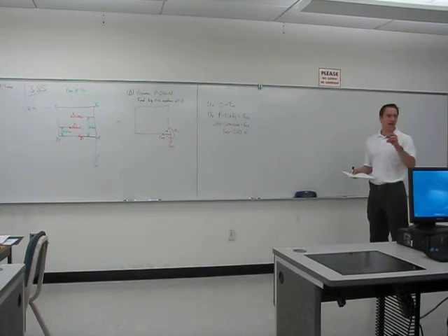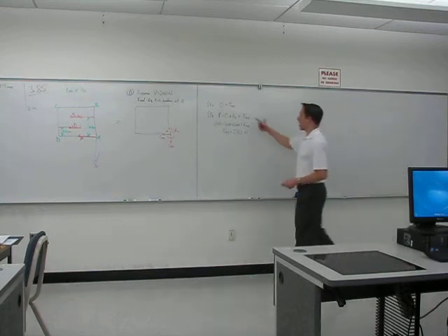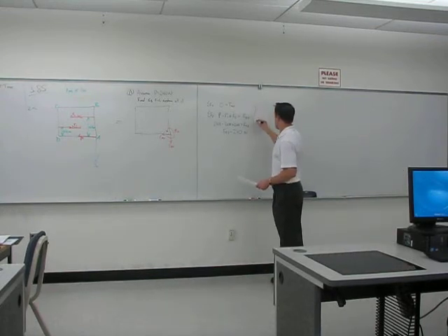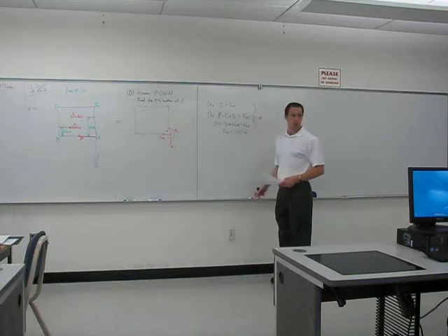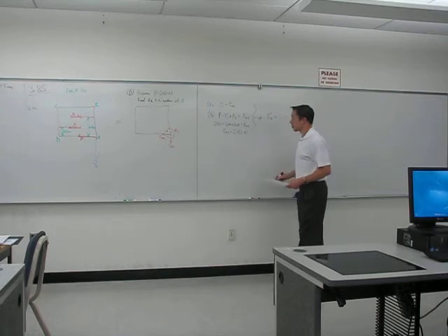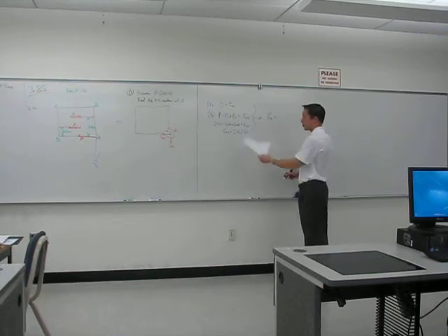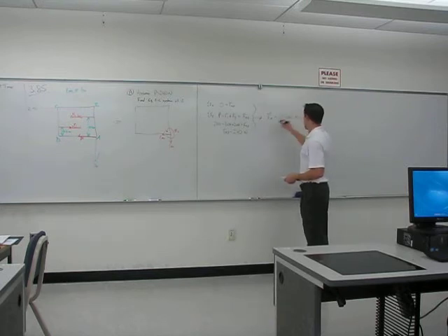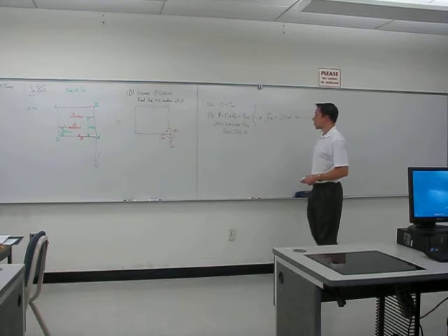So right now, I know what the force is that needs to act at the point A. If I just combine the two results that we found here, what this tells me is that FA, written as a force, has a full magnitude of 240 in the Z direction. Okay, so I might show 240 newtons going in the positive Z direction.